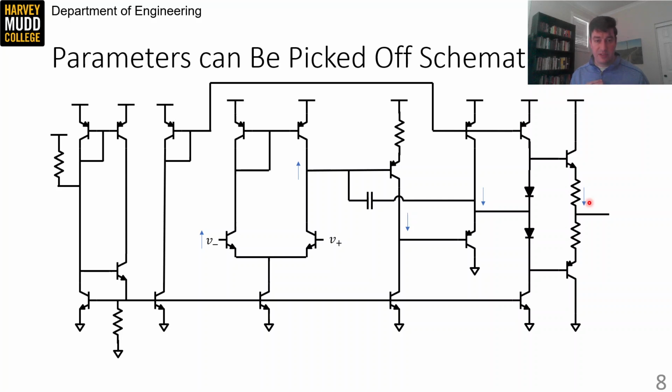Note that I trace the signals through in terms of voltages here, but you can also think about currents running around the amplifier as well if that's easier to propagate. The key simplification to keep in mind when we're finding the input polarity is that you're only looking for a direction of a relationship between these perturbations. So you don't need to calculate exact gains, just think about whether a node will move up or down.